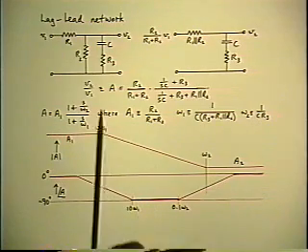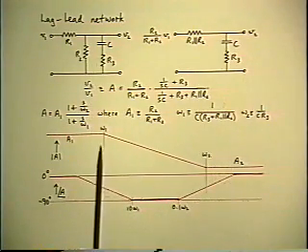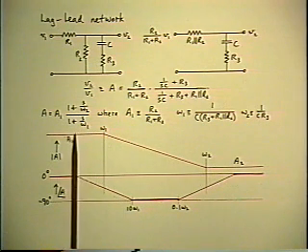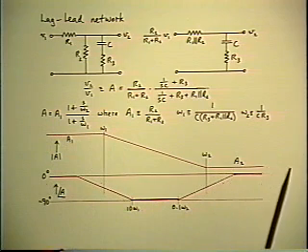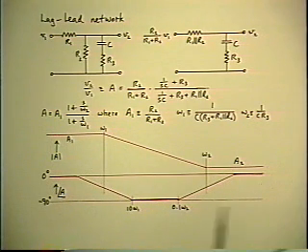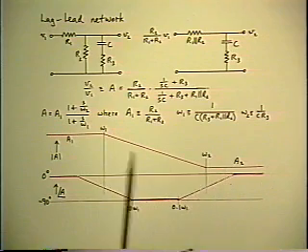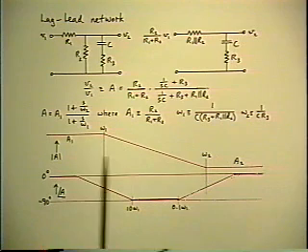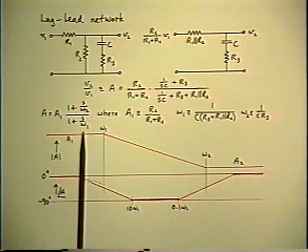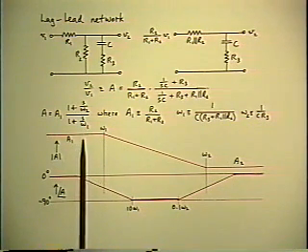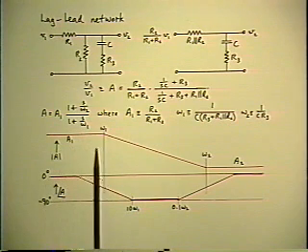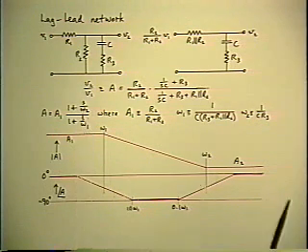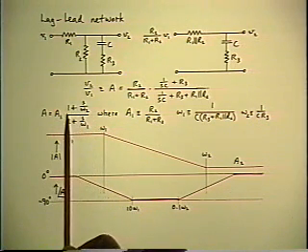But suppose we didn't start with a network. Suppose we started with the diagram, the asymptote graph, and we labeled this flat gain as A1, we labeled the other one as A2, and then I asked you, as we did earlier, to write the factored pole zero form starting from the asymptote diagram. And you see you have two choices. You can either start with A1 as the reference gain, in which case you would write A equals A1, and then you'd look up in frequency and observe first the pole and then the zero, and you would come up with this expression that we started with.